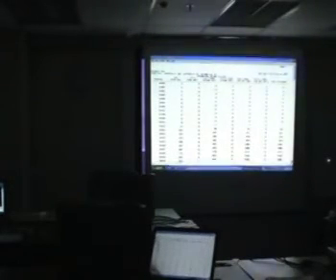So again, it's by every 1 meter. And you've got the cut area, cut volume, fill volume, cumulative volume for cut and fill, and your mass ordinate. Mass ordinate is basically cut minus fill.